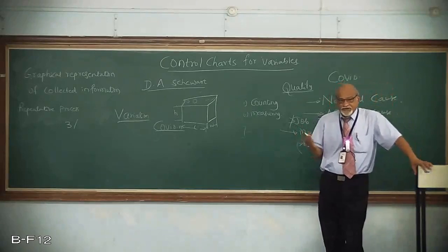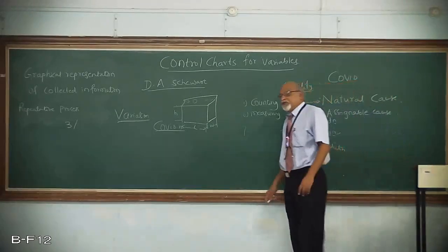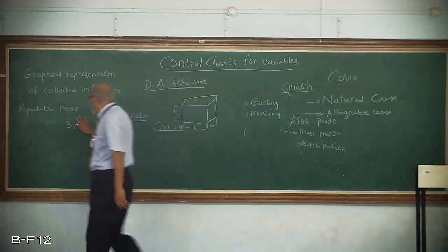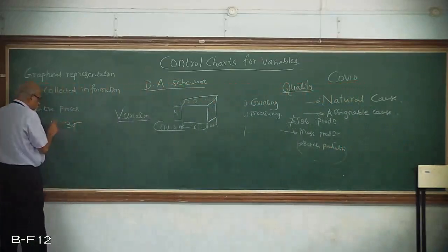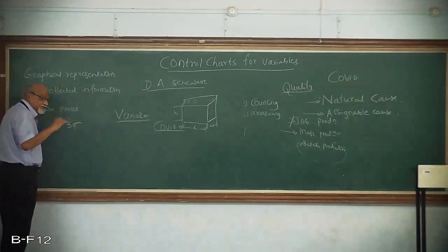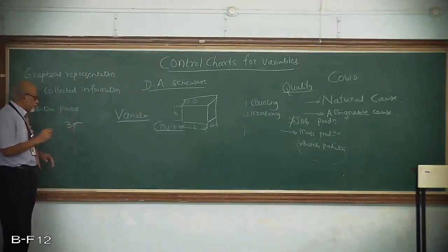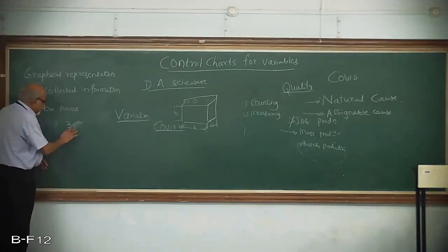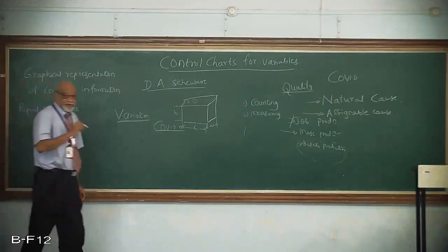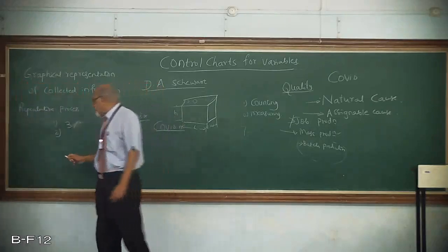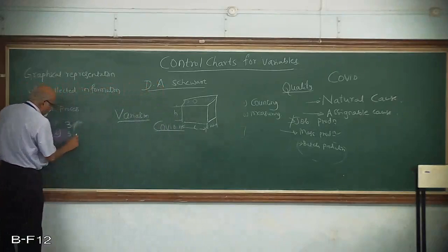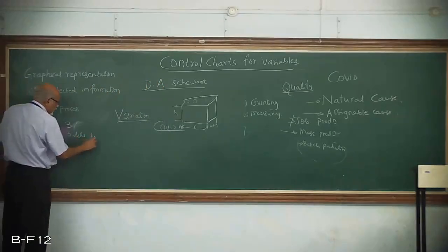But slowly it changed. Then they started thinking, because when we applied the 3 sigma limit, this 3 has got more significance. So earlier we said, if the rejection rate is less than or equal to 3%, it is very good. Failure rate or whatever you can think about it. Then they said, no, not 3%. 3 defectives out of 1,000 items.